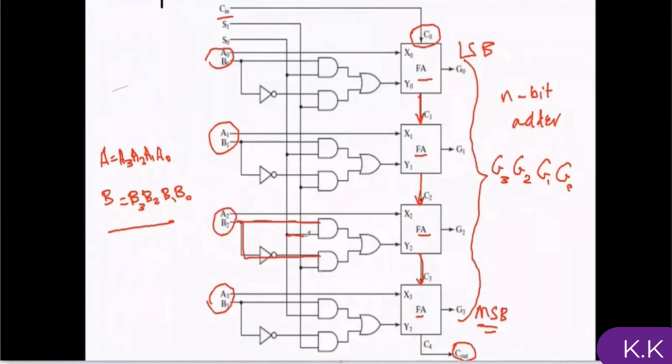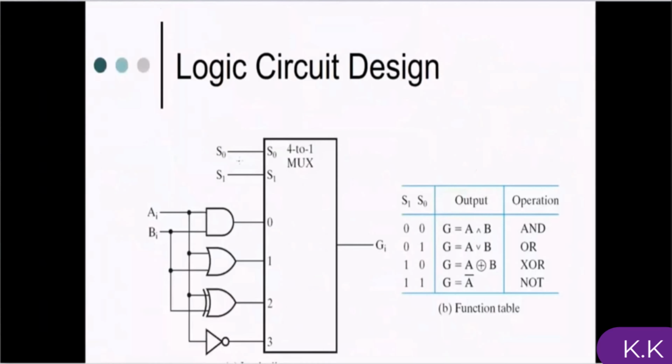And this is the circuit that I talked about. We designed it in the previous part to select between B and B prime using S0 and S1. So as you can see, for example, here, B and B prime are given, here we have S0, here we have this one. This is the circuit that I drew and it is connected to the Y input of the full adder.